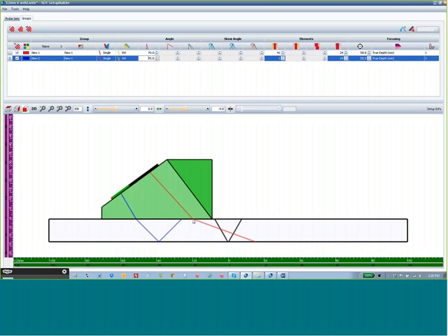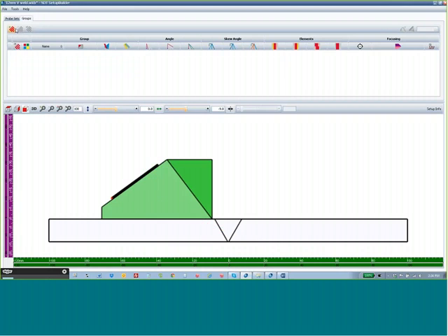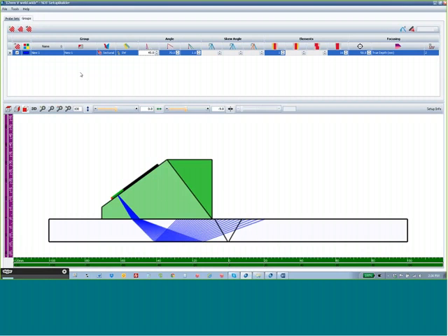Defining the front part and the back part of our scan plan in 2 static A-scans is basically the same thing we're going to do with the compound S-scan. We need not do these static A-scans first. I just did that to demonstrate the idea. So I'm going to delete those 2 groups and create a new one, and it defaults to a standard traditional S-scan where all A-scans are being generated from the same group of elements.